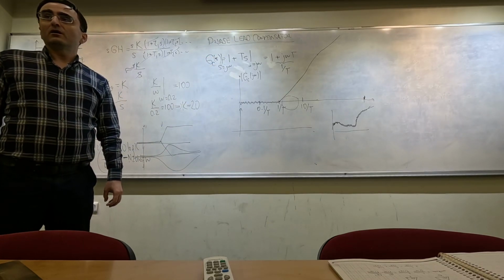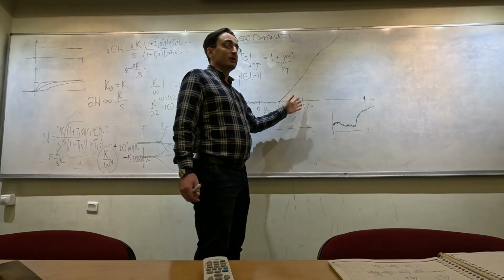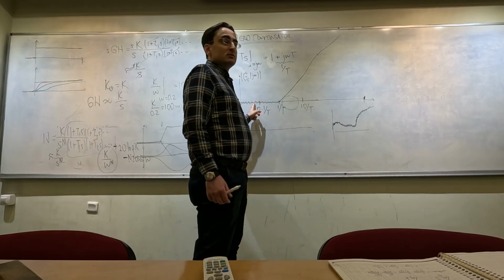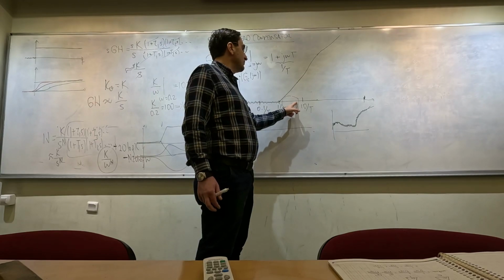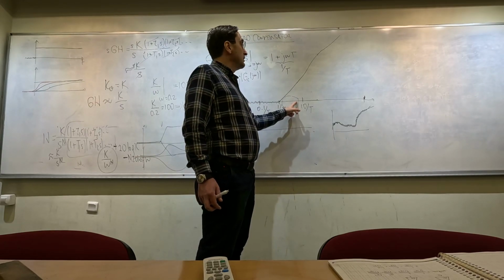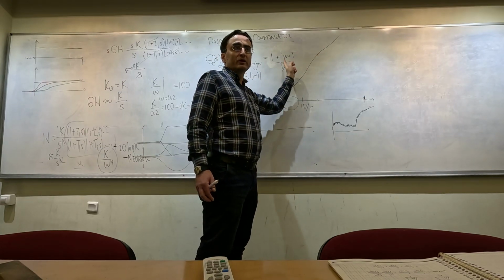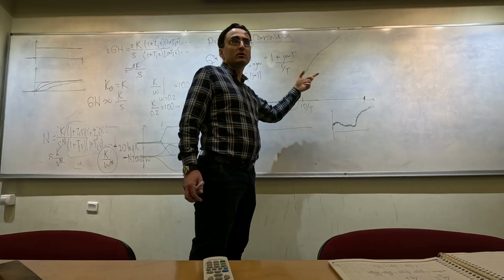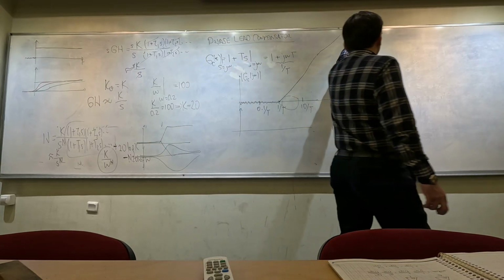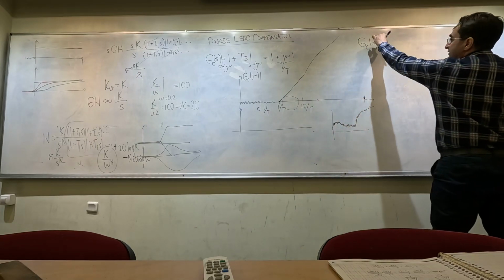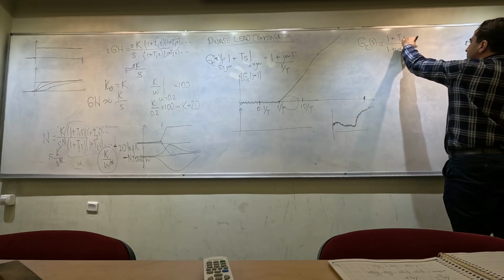Another corner frequency decrease. Yes, I can put another corner frequency here, at high frequencies. In this case, is it going to be a corner frequency for a zero, or for a pole? It has to be for a pole, right? That is what is actually done here. So Gc(s) is going to be (1 plus Ts) over (1 plus alpha Ts).